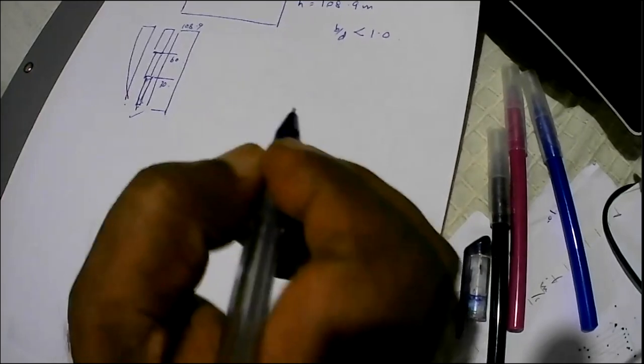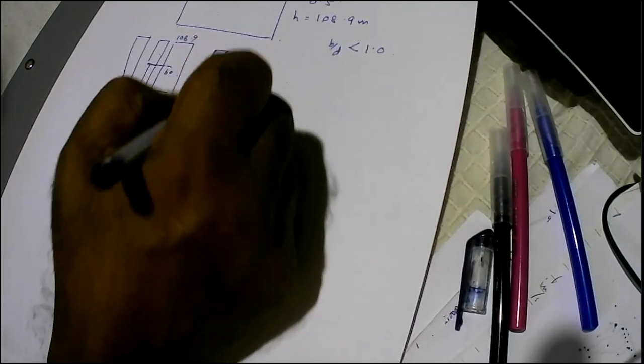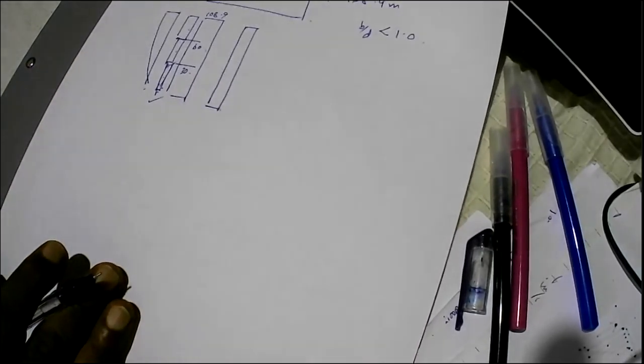So although it varies like this, I will say that it varies like this one, so that I can do the calculation easily. Otherwise, I might have to use a spreadsheet and do the calculation, because the wind speed is varying all the time. Because I'm going to do a manual calculation, I'll divide the building into 3 components over the height. So I'm going to have 3 different velocities, whereas on the rear side, the leeward side, it's a constant velocity, whereas on the windward side, it is variable.